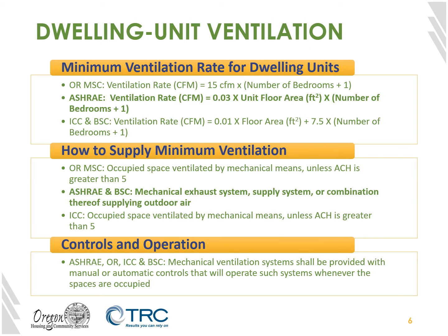So let's see how each of these guides get applied to a building design in practice. First, each guide has a formula to calculate the requisite ventilation rate for dwelling units. While the formulas shown on the screen vary slightly, the end result is a system between approximately 45 cubic feet per minute and 100 cubic feet per minute for most typical apartments.